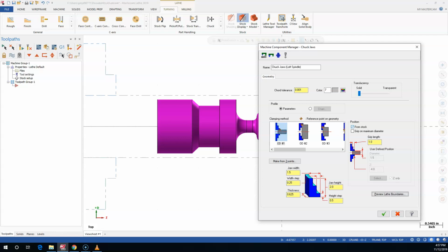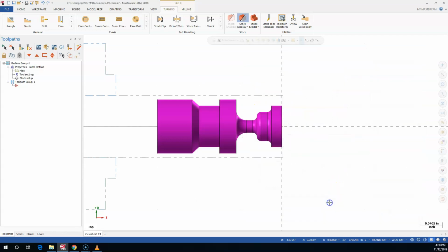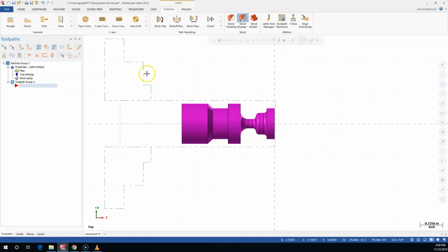So we're going to follow the standard lathe rules of the further I stick this out, the less rigidity I have, the more chatter, the harder it's going to be to maintain that surface finish. So at some point, this is for reference. It really comes down to what I do on the setup sheet, how my setup and my operator are loading this part, and performing those touch-offs. So we still have to manage that information. All right, so again, these are for reference. This is not anything that's going to say at the machine that the machine has to be this way. It's visual for how we're going to program and set our clearances.